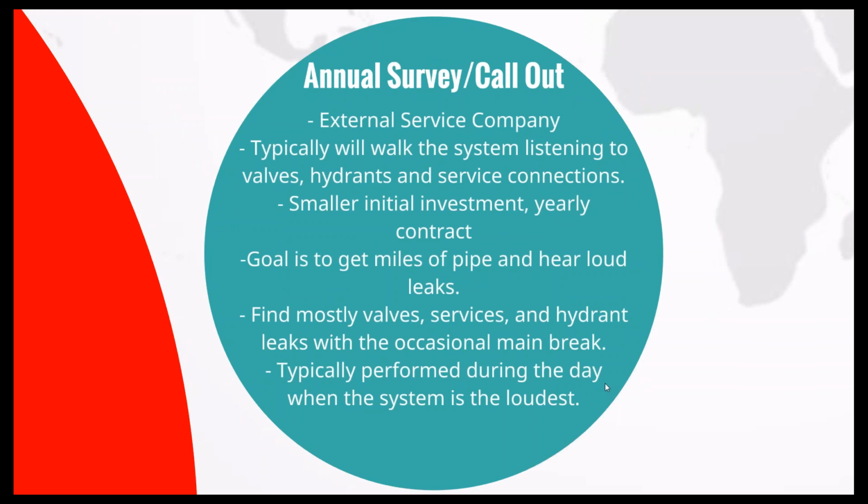So again, hiring an external company, there's a number of them that provide this service. Different approaches can be done, walking the system, listening to valves, hydrants, and service connections. This is a smaller initial investment than probably hiring staff and buying equipment. So it's a way you can, on an annual basis, get through certain parts of your system, and maybe every 10 years you get through the entire system with this approach.